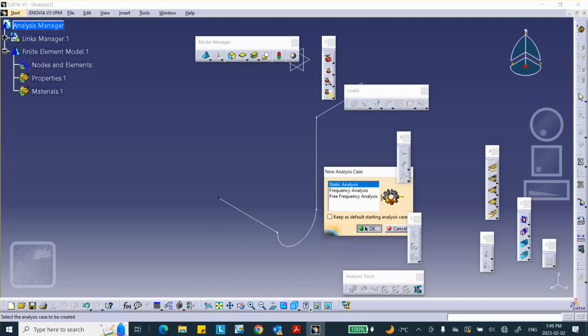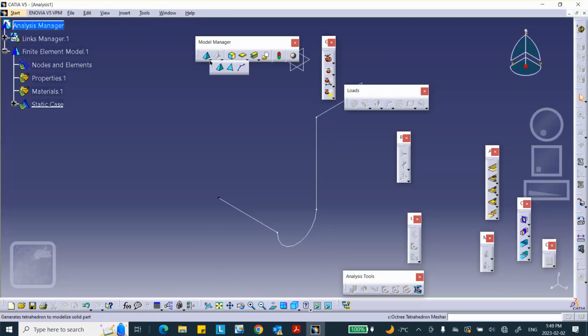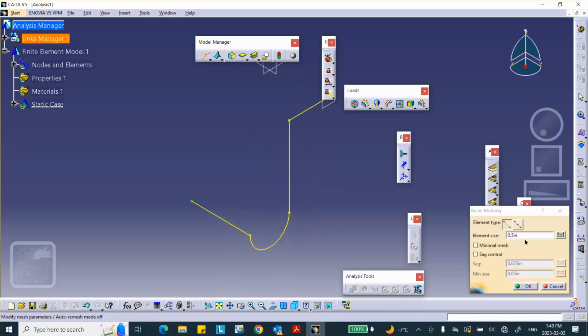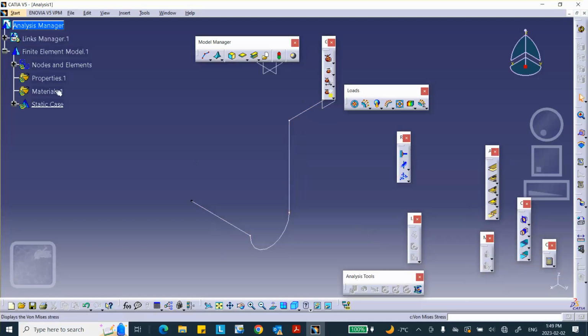And you have to mesh it with beam elements. Because you joined these things, when you click on this, the entire thing is going to get meshed. So you select that, it turns yellow, that's a good sign. Why don't we make the size of this thing about 0.1? So there's going to be, I don't know, 15 elements this way, 20 elements this way, etc. But these are very robust elements, so we don't need that many. With maybe 5 or 6 elements, you can get excellent results.